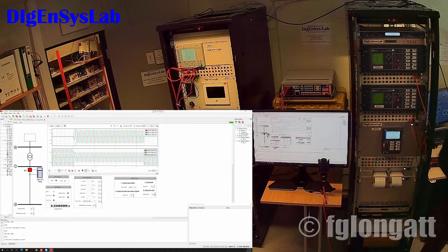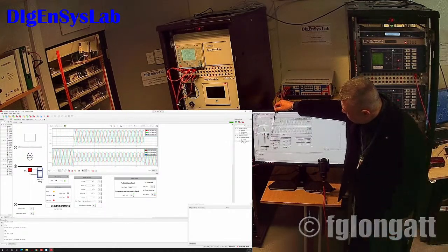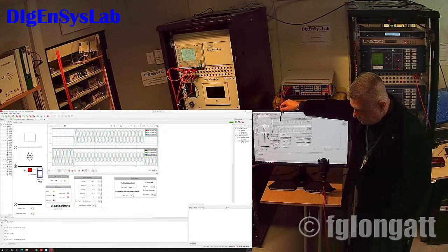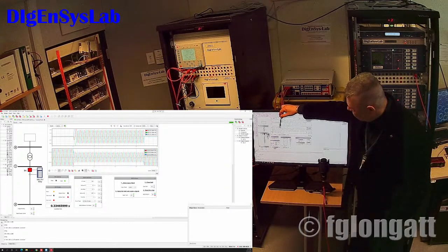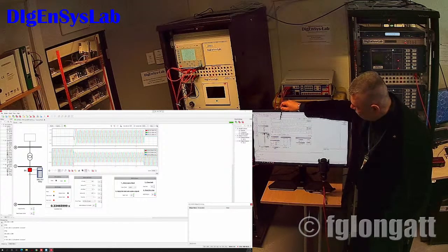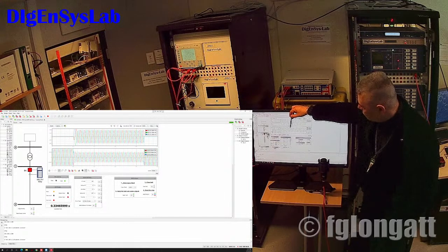After the breaker opens, the current should go to 0, okay? What you see over here is the steady state. Then we insert the fault, the current goes high, and the relay sees this increasing current, okay? And you can see how the voltage is going down because we are in fault, okay?